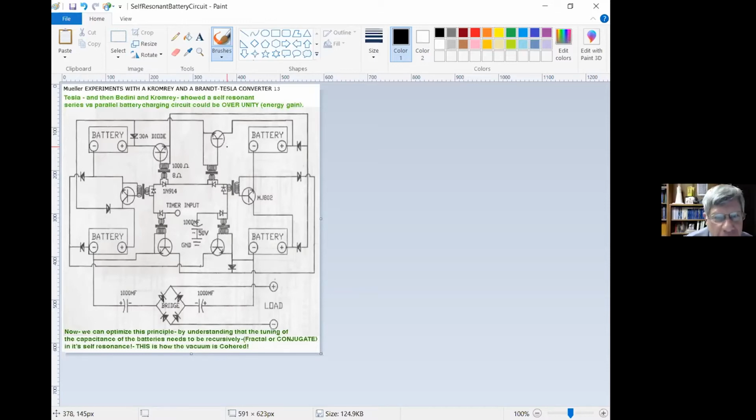Well, yeah, the old way of isolating transistors or any electrical system was transformer coupling, but optical couplers work much better. You can go 4,000 volts with those things. Oh yeah, I've used them before. They're real high voltage and they're fast too. Yeah, I agree. That's why I was saying, just look at how they drew the bridge. That tells me this is some old circuit design.